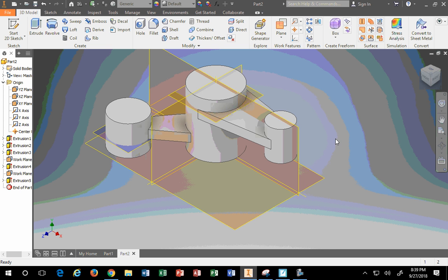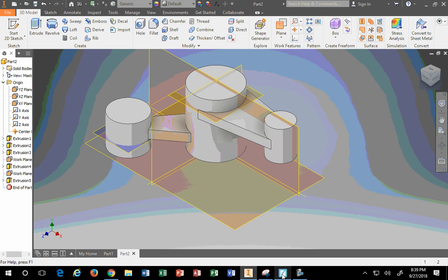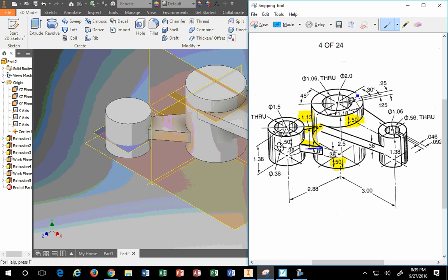Everything else you can build without any conversation, meaning you know how to draw. You know how to draw circles. You know how to make holes. The keyway you will have to build independently of the hole. Please remember that. This object here, you can use the hole command, and then the slot you will build independently. Just extrude cut. What you can't build without a little conversation is this dude out here.